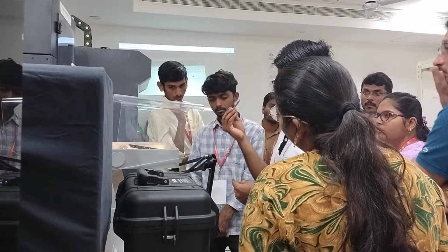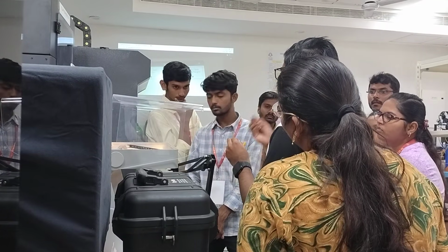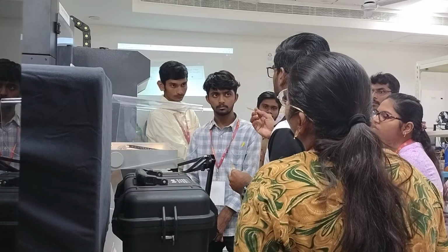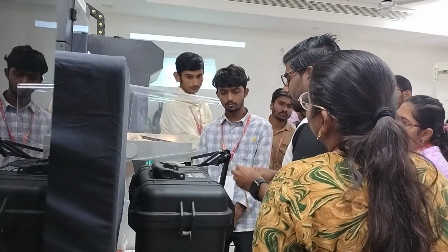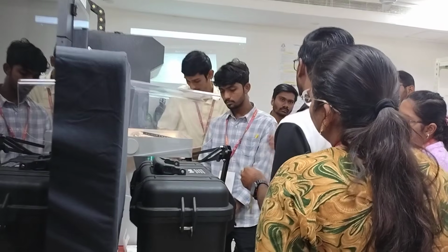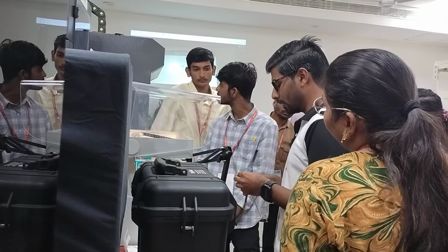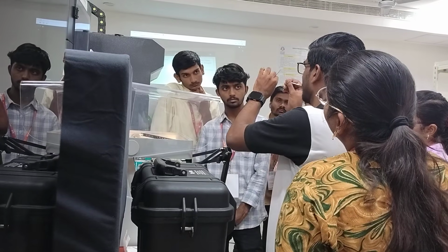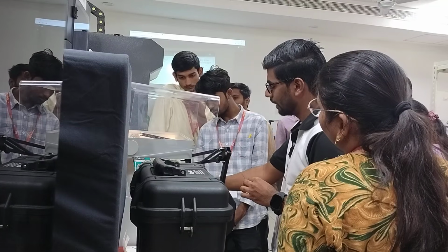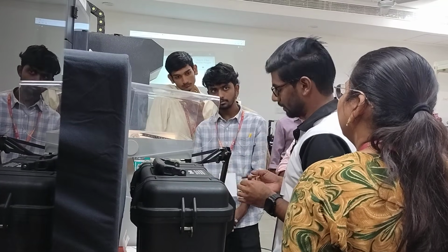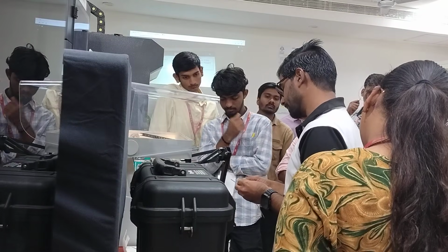This is a tool. Yes. So these shims are basically used to find the clearance between any two parts. We cannot use verniers everywhere, and if there are small gaps, we cannot put the vernier or the gauges there. In that case, these are already well defined, and we just put them in those places and see if there is a small resistance. We say okay, the thickness of that measured part is so much. That is basically called a shim.